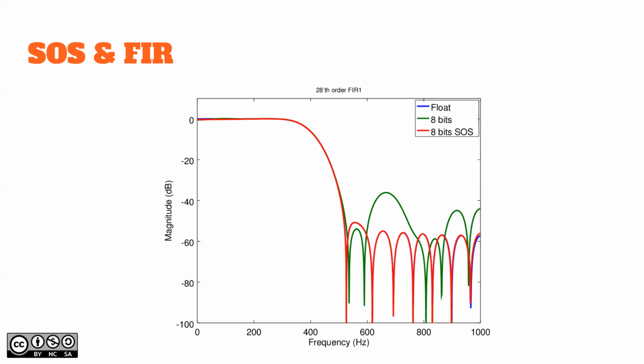And how do you deal with it? Well, you just leave it there, since there will be some errors. You are making some choices here. If you are shooting for performance on discrete time systems without floating point acceleration, then the only way to go is to select the word length that fits your requirements. But anyways, it's not that bad actually.